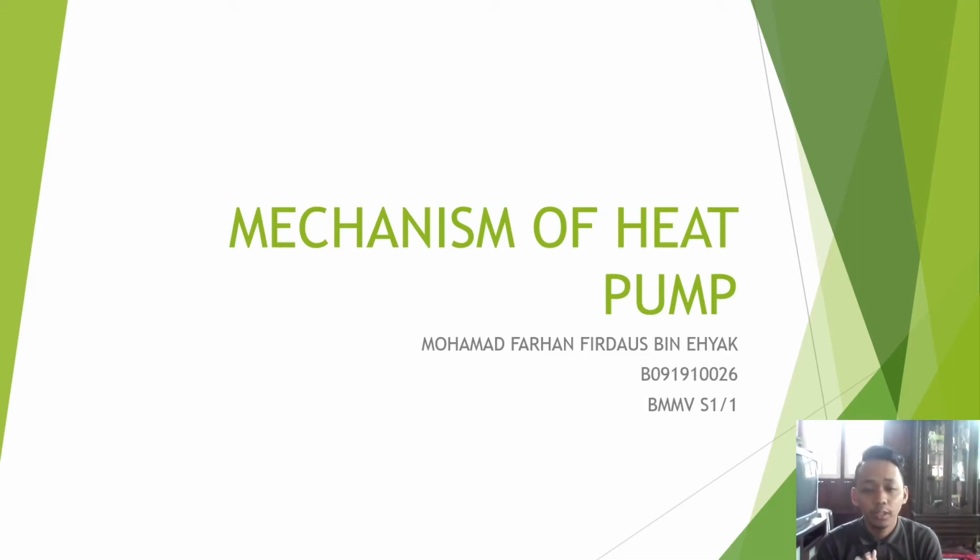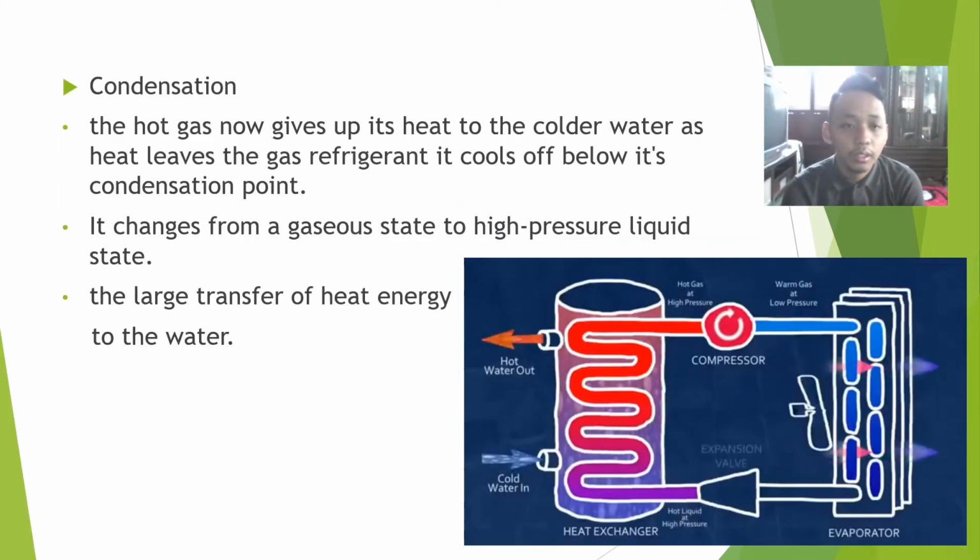Okay, I am going to explain another two mechanisms, which are condensation and expansion. Okay, condensation. The hot gas now gives up its heat to colder water. As heat leaves the gas refrigerant, it cools off below its condensation point. So condensation happens at this point.